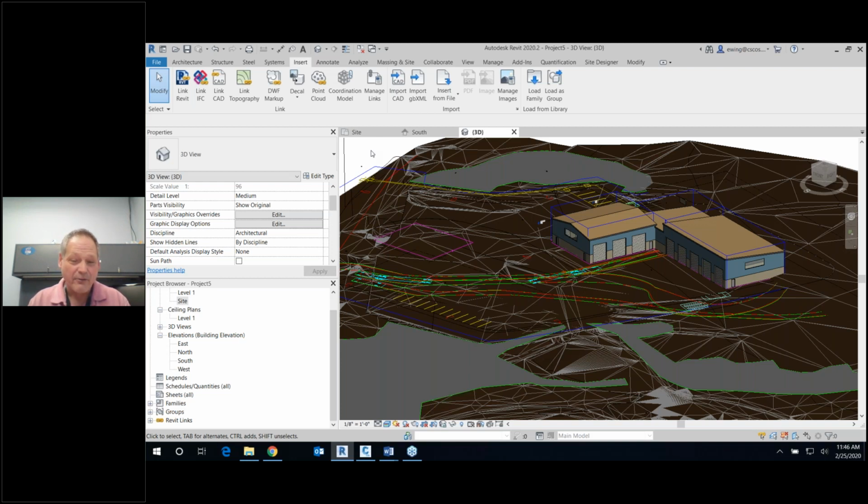Oh yeah, it stresses me out. This is the one thing that stresses me out the most, because this is one thing I've seen fail: shared coordinates. And if I have a normal project, I don't put them on shared coordinates unless we really have to coordinate with the civil engineer. Then I'm going to put them on shared coordinates.